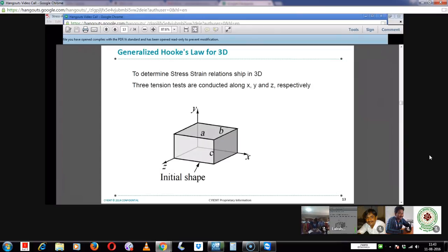One represents the blade mass, another represents loads acting on the blade, and these are joined at the attachment region. This blue color represents the attachment region, and we can do a simple 2D analysis. It won't take much time, but we only need to accurately simulate the blade and blade attachment region. So this will reduce a lot of computational power, and it will give results in a very quick way.